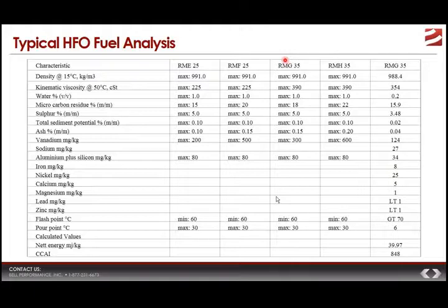Density is also important. It's important to be measured because before marine fuel oils are used, typically they're purified by using a centrifuge. They get run through a centrifuge. Centrifugal force strips out some of the heavy things that might cause wear inside of the engine. In order for this process to work, the fuel oil's density must be different from that of water in order to do this. So that's why they measure the density.